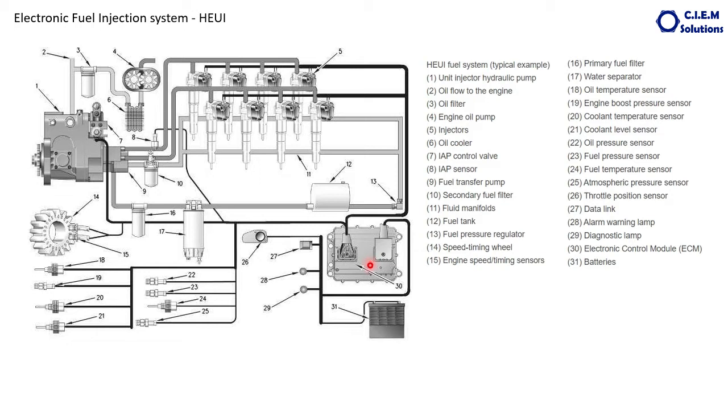This is a powerful computer fitted in the engine. What job does it do? It takes the signals from various points of the engine. First of all, it takes the inputs. After taking the input, it decides what fuel quantity is required at that moment of the engine, what the injection duration should be, and what the injection pressure should be. It decides in a fraction of a second, maybe to a precision of 2 milliseconds. That much faster it thinks and acts.